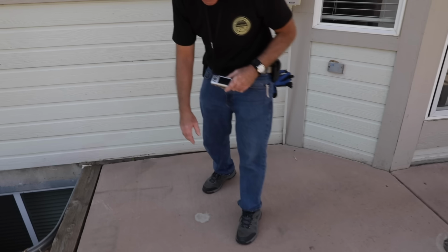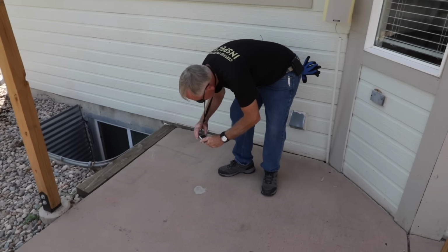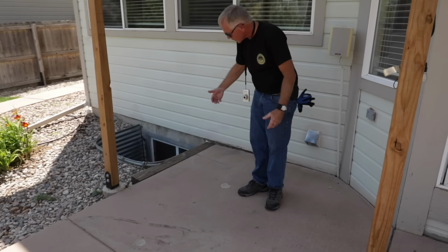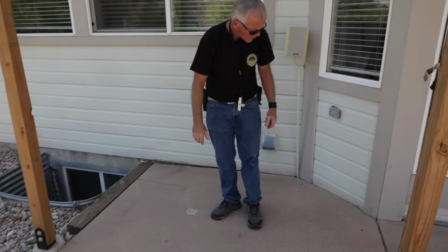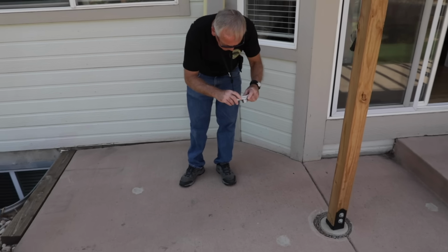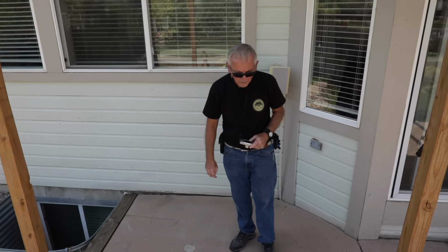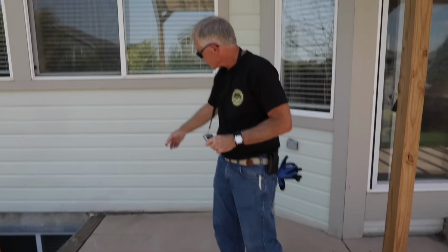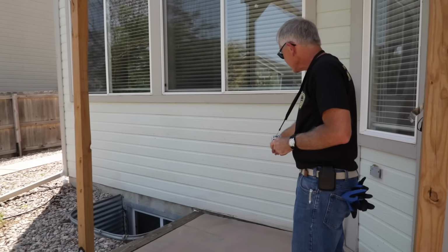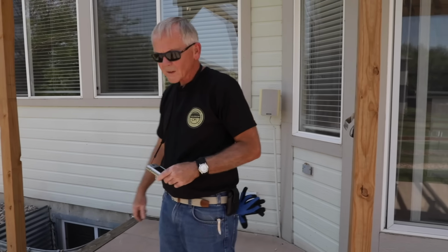But when I turn around, I can see that they've attempted a mud jacking repair back here to lift this pad back up to its normal level, but they didn't get it done. So I'm going to recommend that they get a concrete contractor or a mud jacking contractor out here to correct this, because this is a spot where you could get a lot of water down along the foundation, and that's something we don't want.